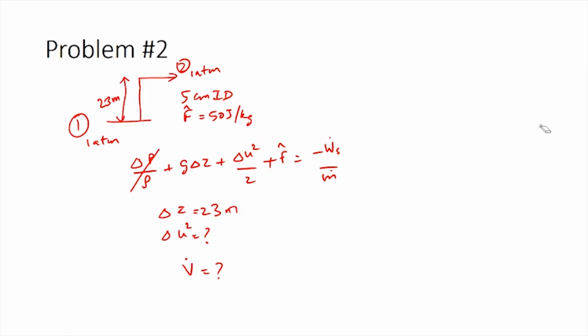As we already have assumed that the volumes are additive, we know the total volume of the final 60% mixture and the initial volume of the 95% glycerol mixture. So, we can calculate the volume of the 35% glycerol mixture using these two values. So, the volume of 35% glycerol mixture would be 2610 minus 1000, giving a value of 1610 liters. So, this is the volume which we are adding. We know that this is being added over a period of 13 minutes, from which we can calculate the volumetric flow rate. From the volumetric flow rate, we can calculate the linear velocity by dividing it by the cross sectional area.